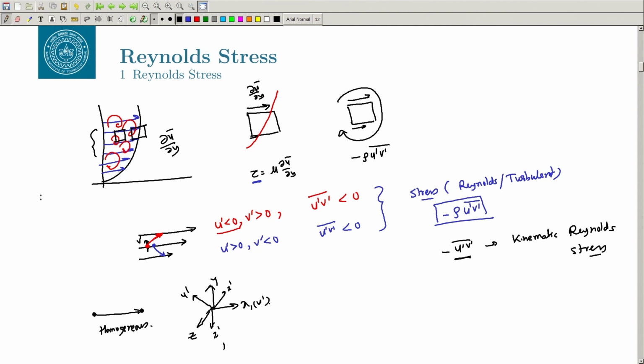Of course, it cannot happen if there is a wall there, right, because there is a motion on the walls, it will impart some directionality. So, it cannot remain isotropic, but for a general flow, let us say the turbulence in a box with all periodic boundary conditions, you can have an isotropic turbulence. In fact, this assumption helps us in our viscosity model. We will discuss that later, right.